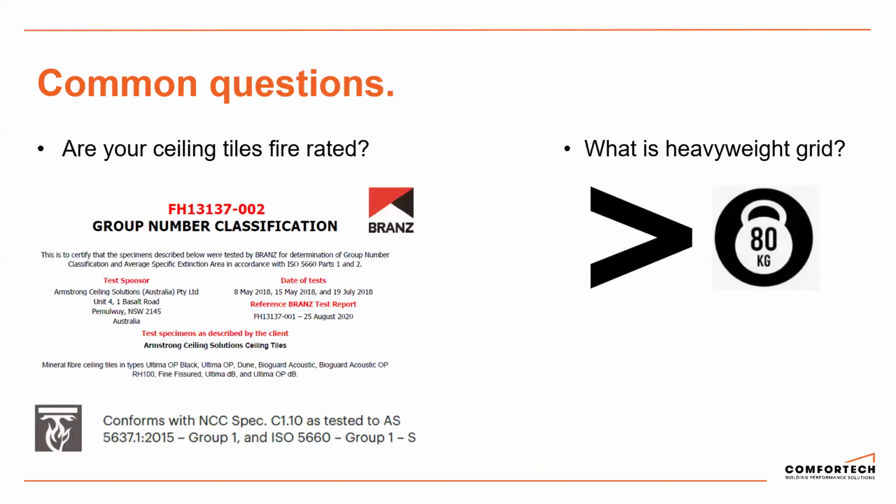So just to wrap up ceilings, a couple of common questions that I often get asked. So one, are your ceiling tiles fire rated? In the past, there was a system on the market that said they had a fire rated grid and tile ceiling. That's no longer available. The reason being is it's so hard to maintain that integrity. You can imagine if someone comes in and lifts ceiling tiles to access services, if that ceiling tile is not installed correctly, there's your integrity of your fire rated ceiling.